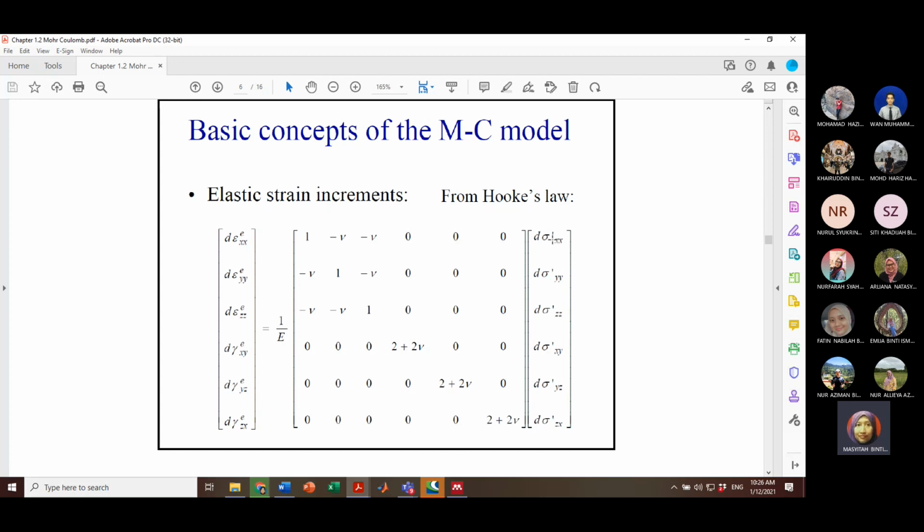The stress increment is the stress acting in a direction on the plane where it is. So if you see here XX, YY, ZZ, XY, YZ, these refer to where it acts and on which plane it acts. Then when you talk about Young's modulus, there's another parameter that can also be obtained, which is the Poisson ratio.